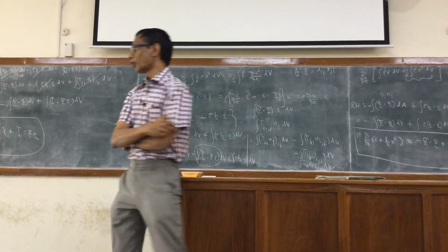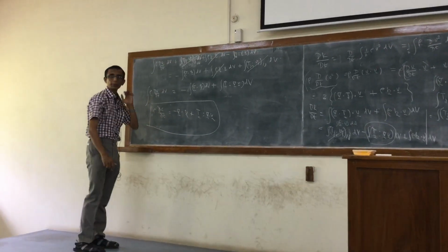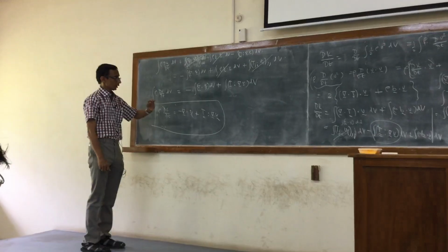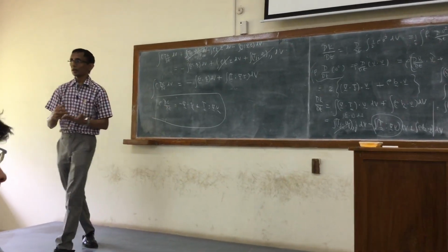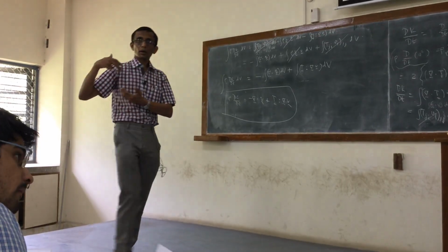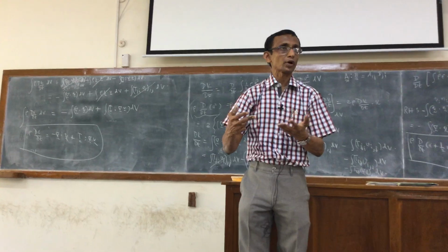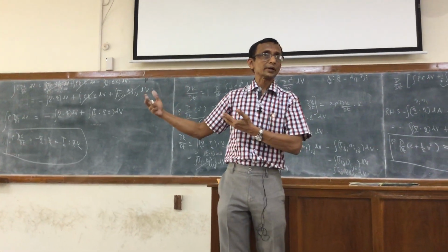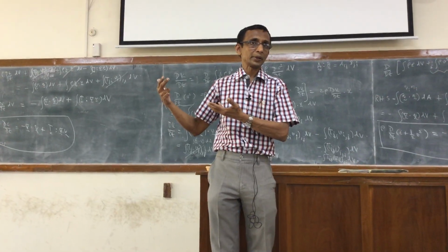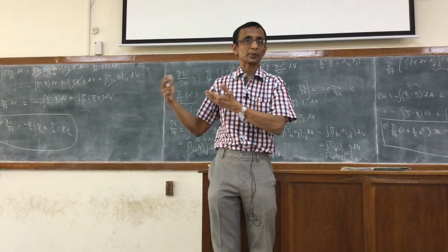Anyway, if you didn't quite follow the intermediate step, at least the final expression you should keep in mind. So there are three quantities here, right? This is the energy balance. As we saw, we developed the equation of motion, and then we said that we need to specify what the stress tensor is. We also need to specify the body force to solve the momentum equation. And then we looked at the linearly viscous fluid, compressible versus incompressible, and so on.